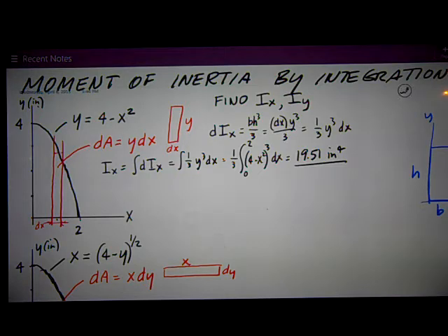For Iy, I want to use the equation on the equation sheet, which is that Iy is equal to the integral of x tilde squared dA. In this case, x tilde is the distance to the centroid of the differential element dA, so it's just whatever the x value is along that curve as you integrate it. So x tilde is equal to x.